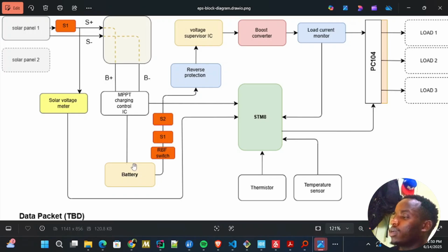Now remember, these batteries can be removed from the board. So when you're inserting them into the board, assuming worst case, assuming all of these other items are on, and you insert the battery pack in the reverse direction for some reason, then this reverse protection should kick in and not allow reverse connection to the ICs on the other side of the board.